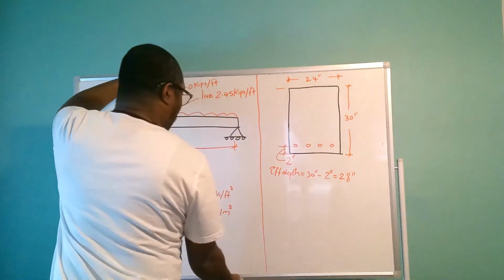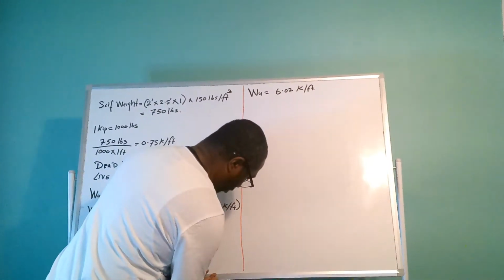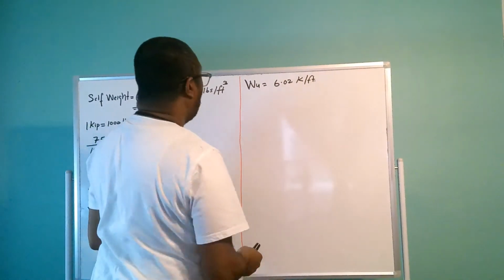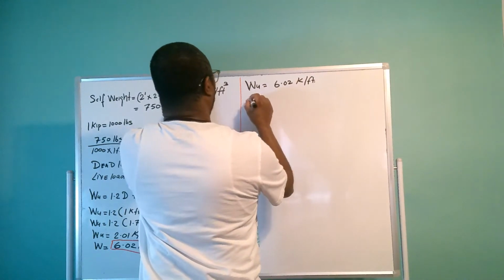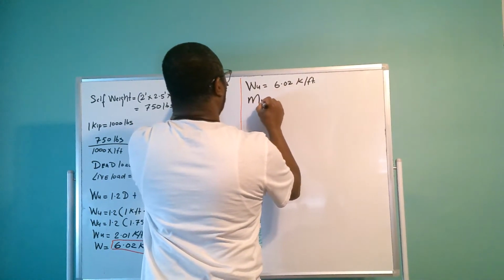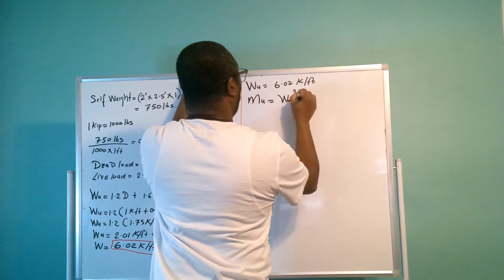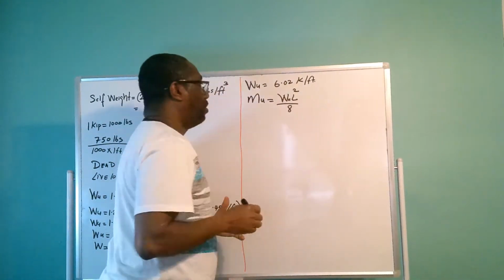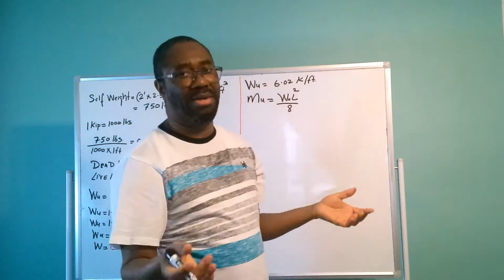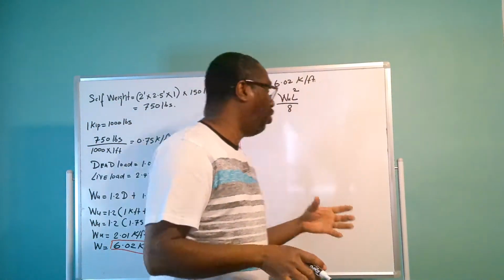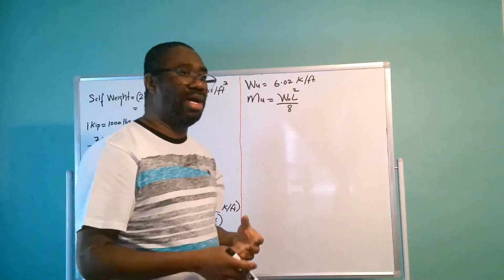As I have shown you before, the moment is WL squared over 8. So we do not have to go through the rigors of plotting the shear force and bending moment diagrams.